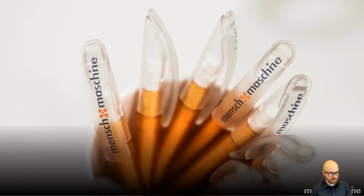Next question from Reese. Do we need to recreate and publish new 3D views in all the Revit files for specific levels to show up in the model coordination tool? The model coordination tool as it stands uses the published views from Revit. So there are different workflows you could go through to create the views you might need. I broke it down by floor, which is quite easy to do inside of Revit. You could use view templates to create specific views, and you could share those view templates with other companies as well, to be able to create the views that you want.